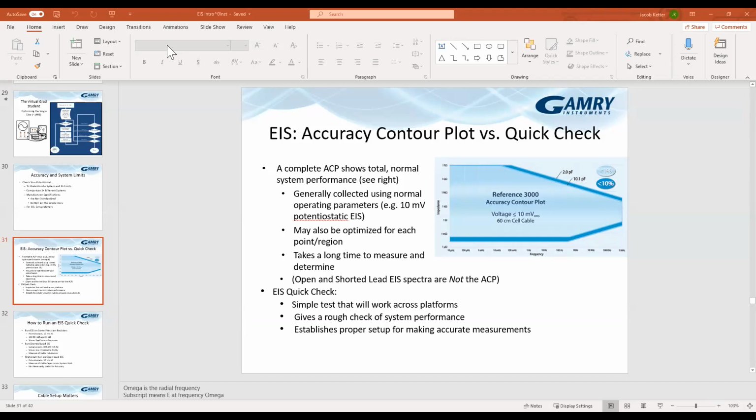But there are limitations to how that can be applied. A lot of coatings analysis just uses the constant phase element and looks at the alpha value for that. And that alpha value is used as an indicator of coating quality for some coating types.